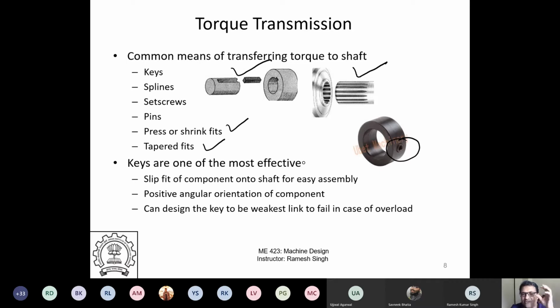Yes. So the vibrations will be much lower, eccentricities will be much tighter. So for precision components, where you want both the centers to be perfectly aligned. If I am rotating, I have machines in my lab which rotate at 150,000 RPM. Now imagine if there is any misalignment, the whole thing will just go awry, right? I have no room for any eccentricities there.